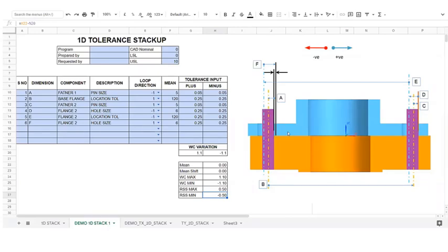But if you try to assemble this in practice, if you see some interference, you can move the part towards the right and then assemble. If manual adjustment is possible, then it's easy to solve. But we need to know how far it can be adjusted manually.